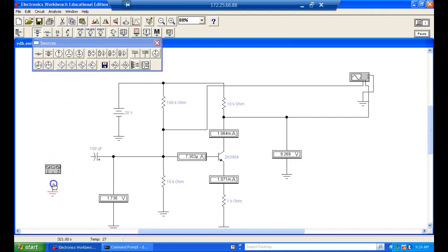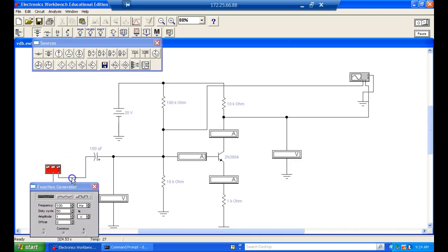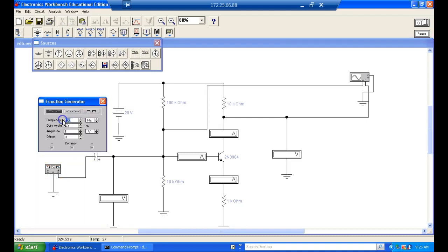Now we have to figure out what this thing does. I can't remember if it's RMS or what. We set the output voltage. So we'll come over here and hit this right here. And then we'll put a 1K signal into it, and it's a sine wave. 50% duty cycle means it's going to be a sine wave. Amplitude I have is 1 volt. So we'll measure and see what it says.